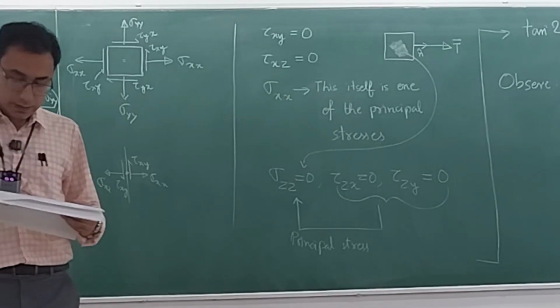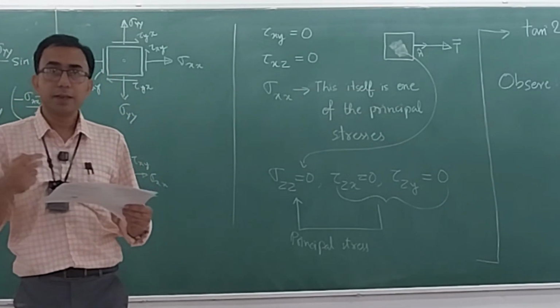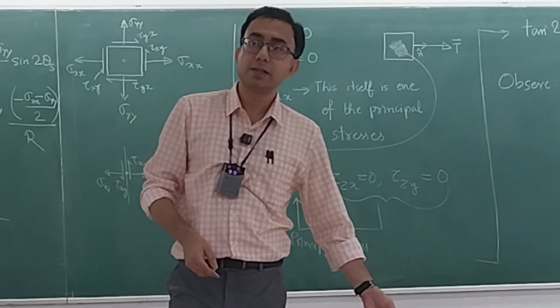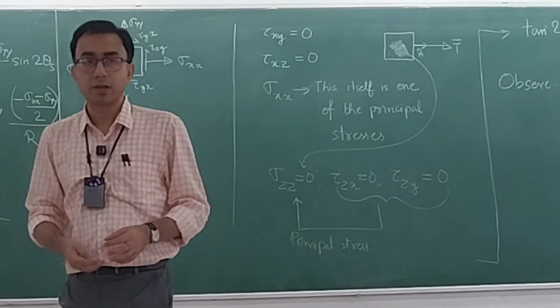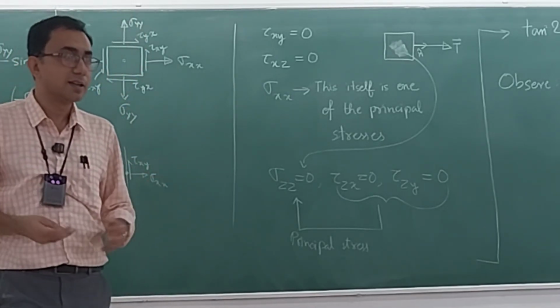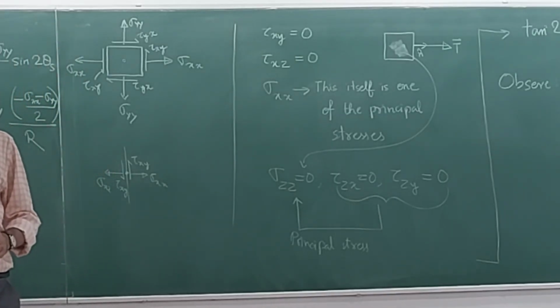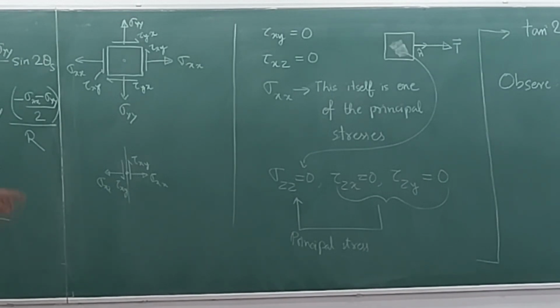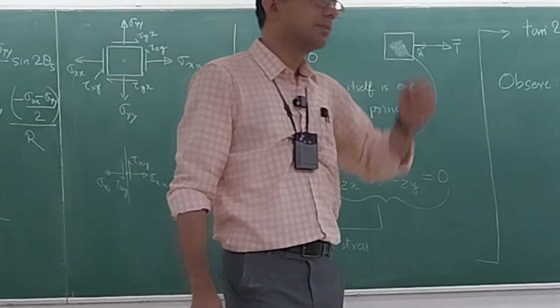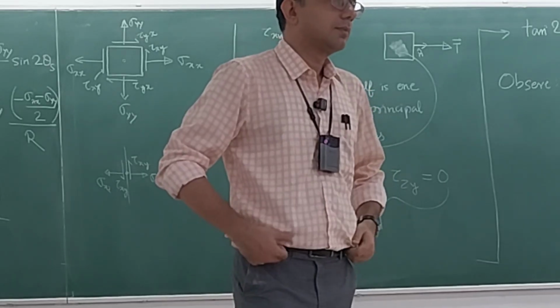So in this question number 10, ultimately when you do it, you will find that there are three circles. That is what is referred to as the three-dimensional Mohr circle. It doesn't mean that you have to draw circles or spheres in 3 dimensions. It's just that you have to draw 3 circles. Okay, and you will be identifying 3 principal stresses. Let me finish. So in that kind of a situation, that sigma zz equal to 0 will also be one of the values. Yes, Charit. So what is the condition in which sigma is equal to 0 and tau has some maximum value?